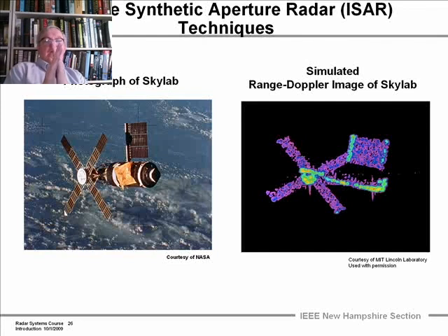And if you know that it's a rigid body, you can relate the cross range to the Doppler velocity. You will get, and you can put them together, those scattering centers, and if they were all over a 3D object, you could pile it all together and make an image of the object.